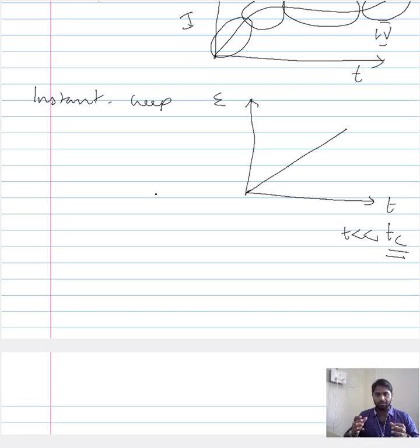We have an idea of how a material behaves under imposed mechanical conditions. For that we plot the stress strain curve, and we see that the typical stress strain curve would look something like this. It comprises the elastic region and the inelastic region. Now, having known that, if you think about what could be responsible for the instantaneous creep when you suddenly impose a definite load, you could say the first response of the material would be elastic,